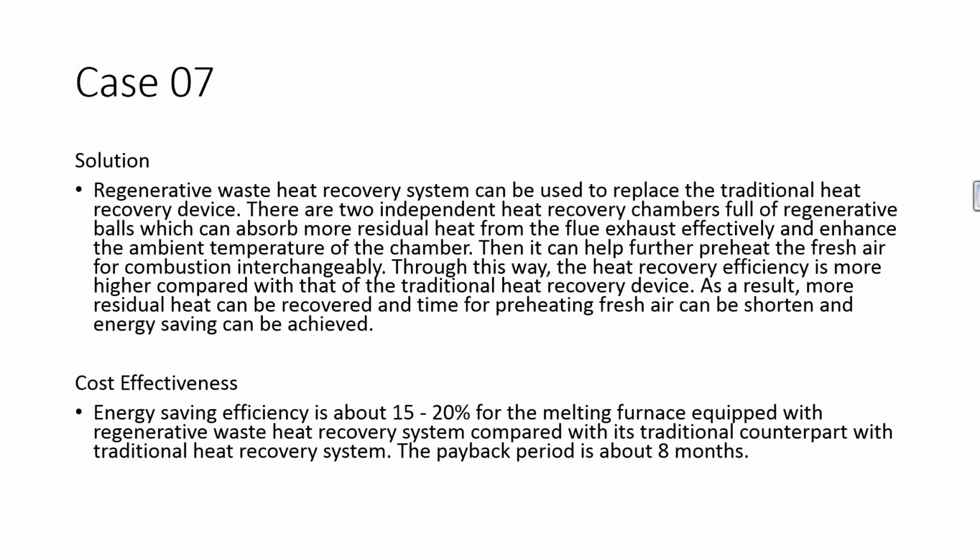Through this way the heat recovery efficiency is higher compared with the traditional heat recovery device. As a result, more residual heat can be recovered and time for preheating fresh air can be shortened and energy saving can be achieved. The cost effectiveness for this: energy saving efficiency is about 15 to 20% for melting furnace